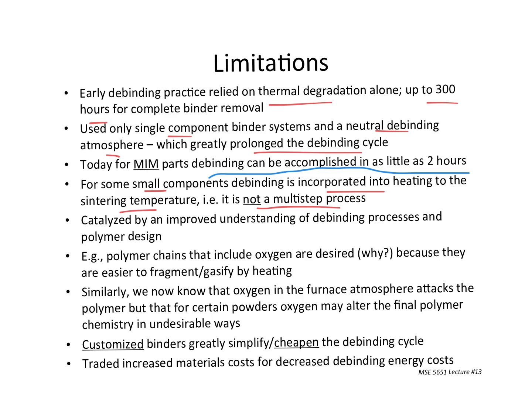But these types of improvements, even for the small parts, are catalyzed by an improved understanding of the debinding processes and also polymer design. We haven't talked much about this. I've been throwing polymer names at you, and those names are associated with what we know about different polymers. So polypropylene, very familiar, everyone works with it.